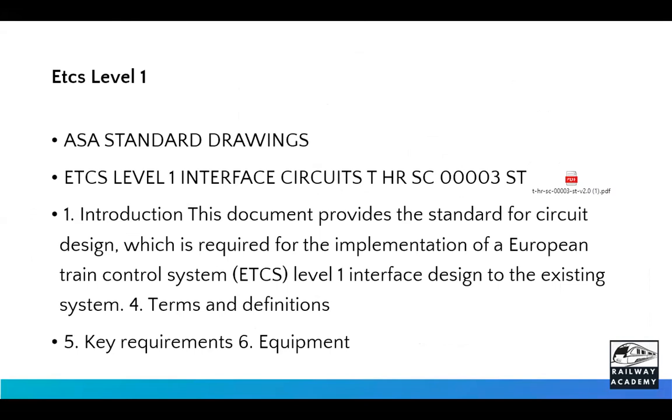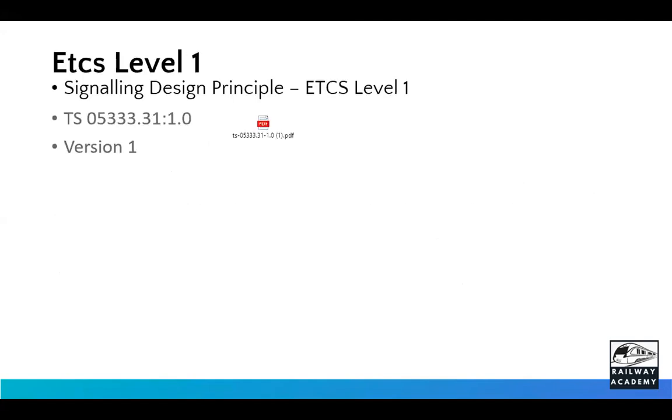Then coming to ETCS level 1, I have already given you a glimpse of what is required in ETCS level 1. It is an interoperable system employing trackside balises and the interlocking equipment, electronic equipment, LU, line side electronic equipment, to take the information from the signals or points or stop board or buffer stop, convert the data into messages, feed it to these balises, and then transfer it to the onboard engine. All this is covered under ETCS level 1.